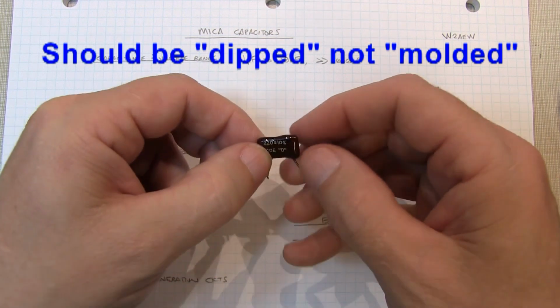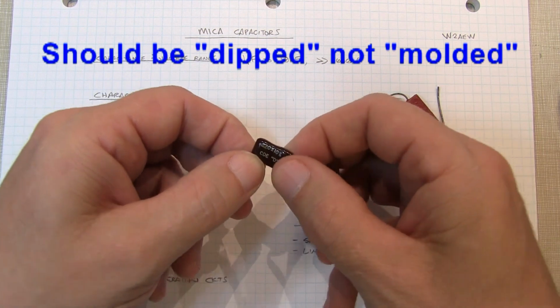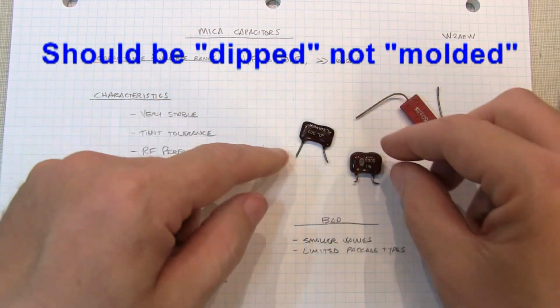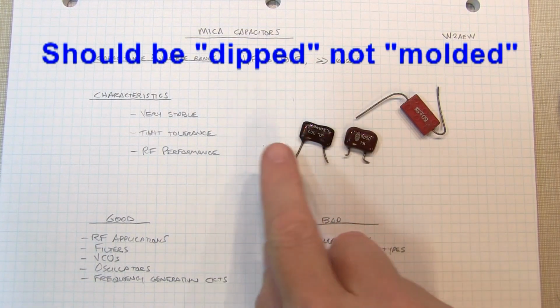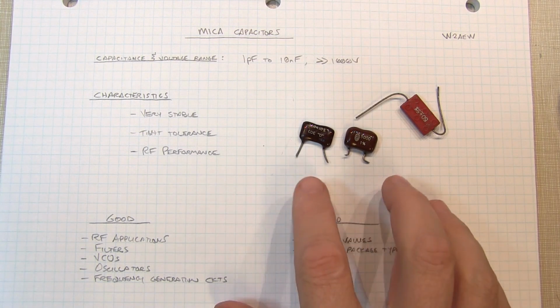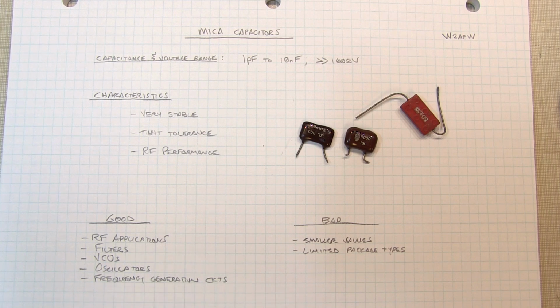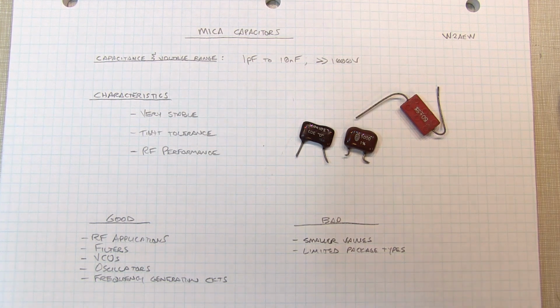That's almost the only way you can really tell whether that's a mica capacitor or a film cap, because the molded caps kind of look the same. But generally, if it's kind of a lumpy package, that would almost tell you that it's a mica capacitor. And also, you can often tell from the application. If it's in an RF circuit, a VCO, or something like that, if a mica cap was available, it likely would have been used in that application.